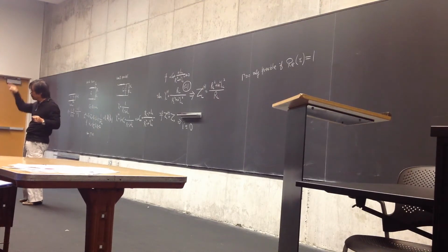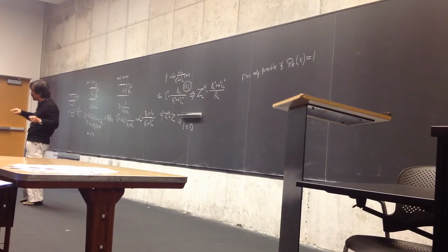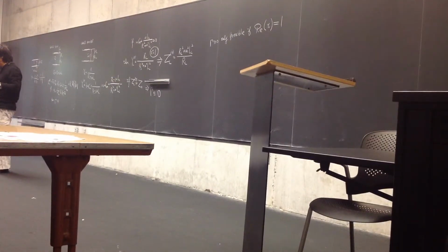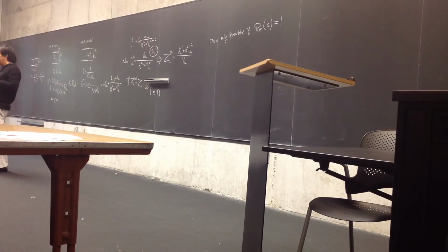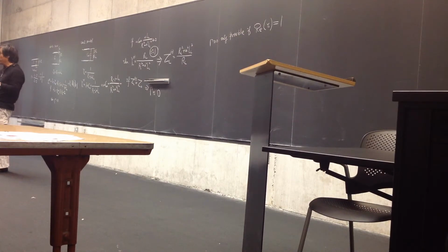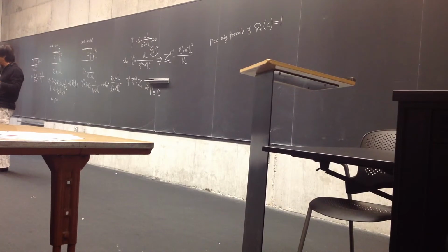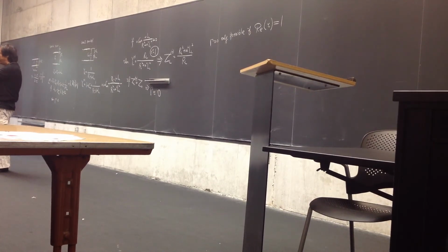Constant radius circle. On the Smith chart, we also see there's a lot of circles, and there's a circle on the top and on the bottom. So you want to have the admittance real part equal to 1. What does that mean? This constant radius circle needs to intersect the R equal to 1 circle. And that is the location that I want to match. So you go from there to find out how many wavelengths I need to rotate on the transmission line to get to this point. When you get to that point, you will have a value of YL equal to 1 plus something, 1 plus jX.